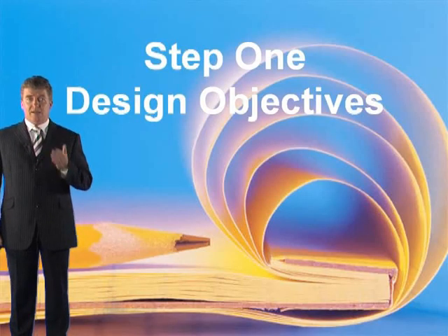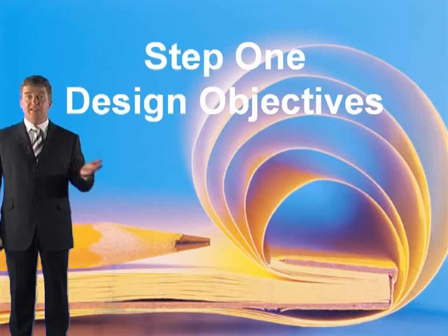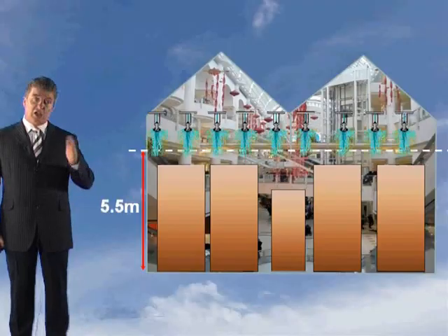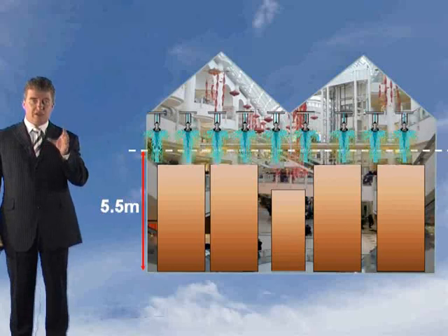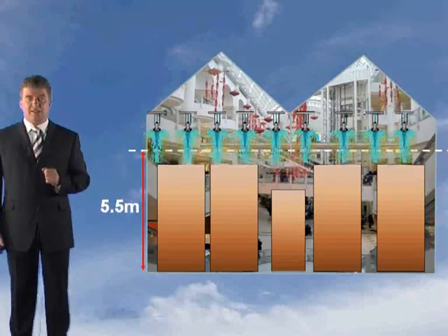Right, let's go through this exercise then. As we said, we wanted you to go through the 11-step guide. Step 1, determine the design objectives. Now, this is specified in the question. This is property protection, and therefore the ventilation system must ensure that a clear layer height is maintained 0.5 metres above the stock. So that was step 1, that's the design objective.